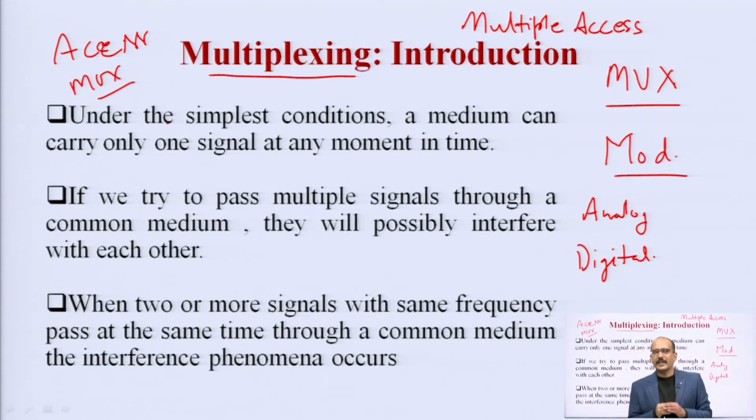You have to differentiate between these two techniques, because in multiplexing, you have n number of users and out of n only one user is using that particular line for the transmission and all other users become idle at that time. But in multiple access the same line is used by all users at all times.